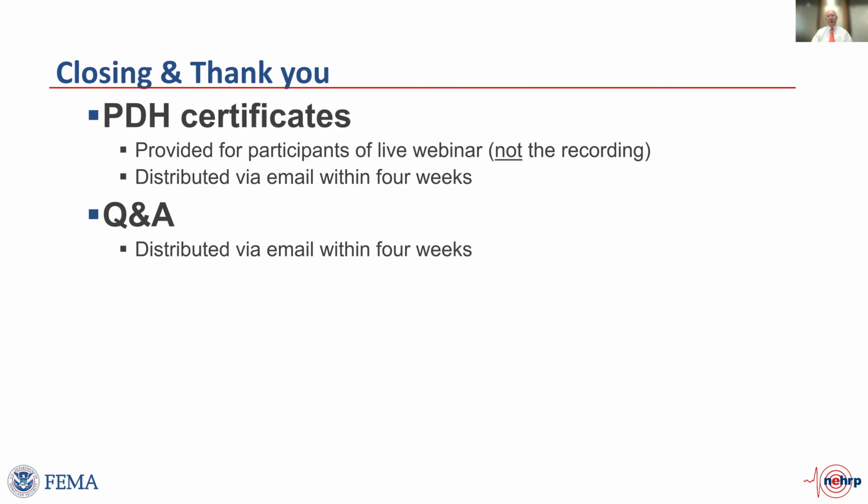So turning this around, the challenge we had was there were a series of irregularities where the implication to design was you're not allowed to do ELF, you have to do modal analysis if you have this irregularity. And the difficulty there is we were requiring people to use the modal analysis method.